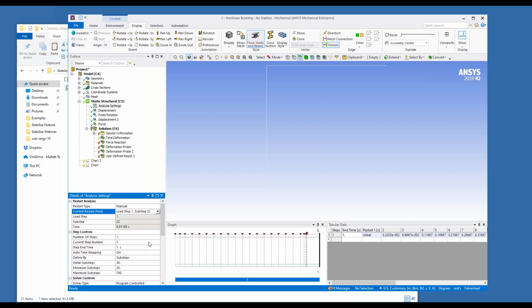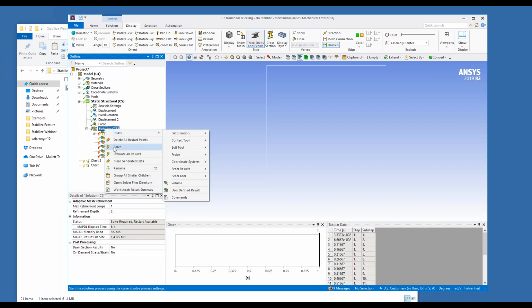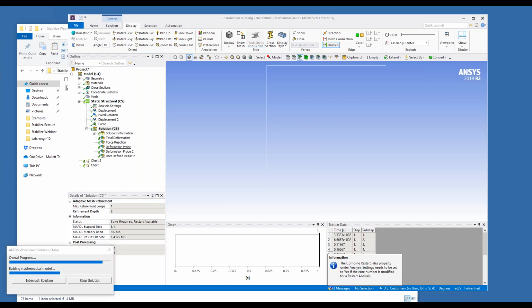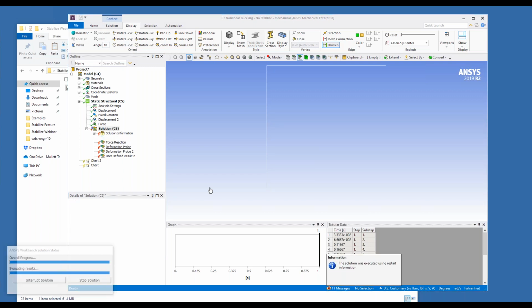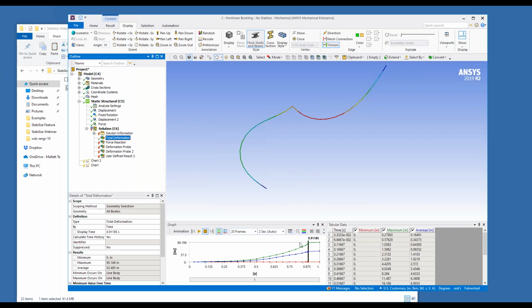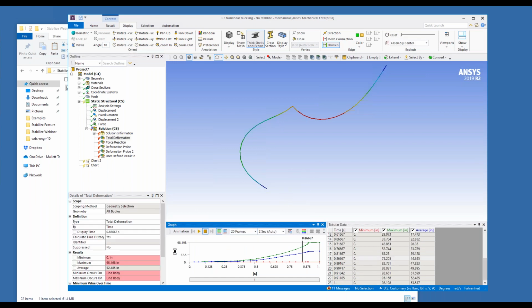If you do that, if you take this and say solve blindly like that, it will not converge because it's starting with large forces. It just calculates at the beginning large forces, damping forces. So what to do? And you can see here, it didn't converge. Again, we have the same challenge. So one way to tackle this is you go back and say, I don't want to restart from there. I want to look at the solution here and restart somewhere here, okay?